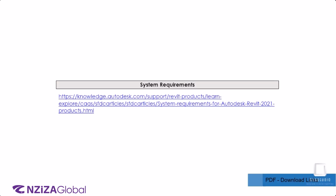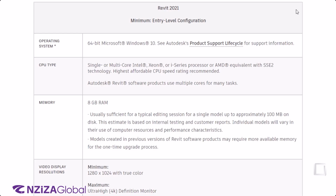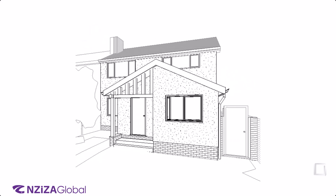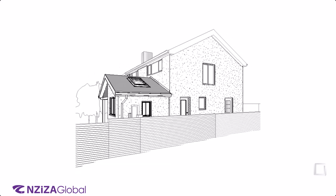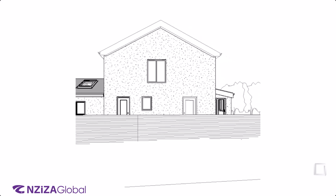Autodesk provides guidelines on the requirements to run different levels of models. The first is the minimum, which is an entry-level configuration. And this is also what is required to run Revit LT. This allows for a typical editing session for a single model up to approximately 100 megabytes on the disk. An example of this will be a small housing project. You will find large models, high CPU usage tasks, and renders will slow the computer down.